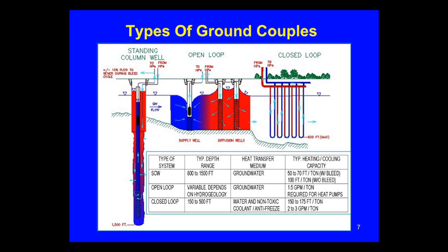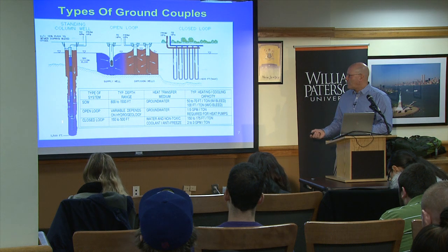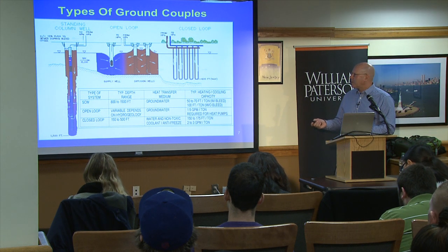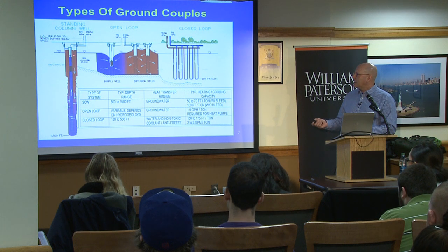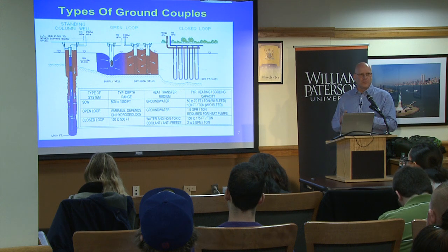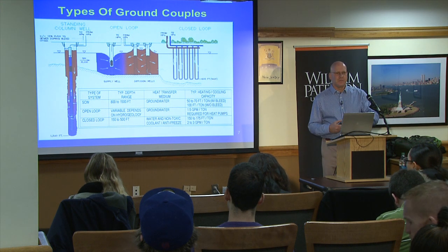Inside that borehole, there's a casing and a screen. The screen allows water in. It's almost like having a straw in the ground with holes on the bottom of the straw to allow water to get in. The water is pumped up by the pump, goes out to a heat exchange, and then comes back in and circulates all the way down to reach an equilibrium to exchange heat again.